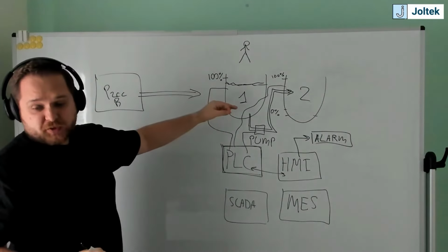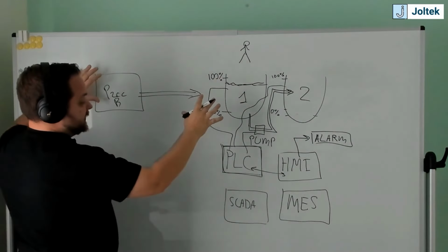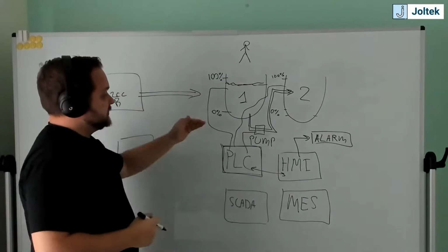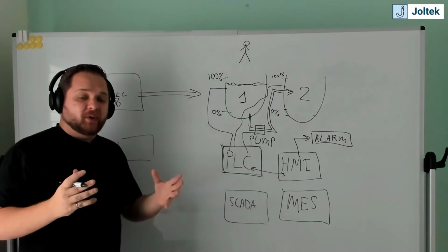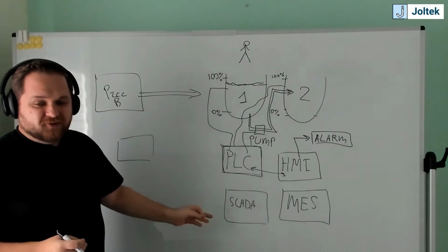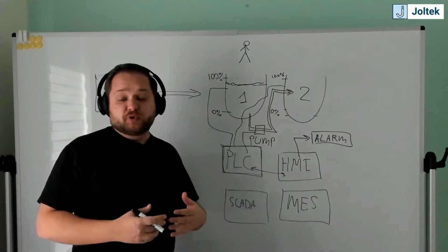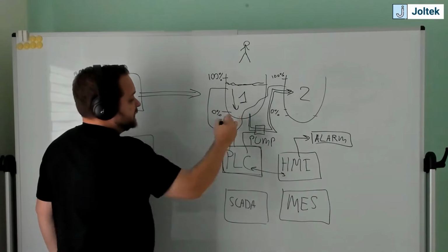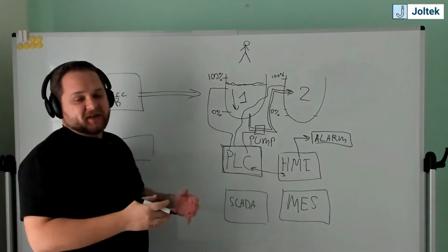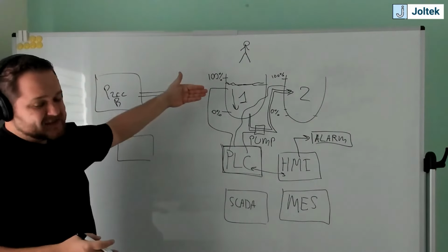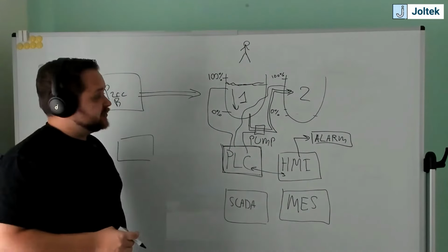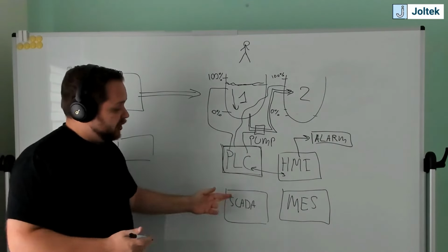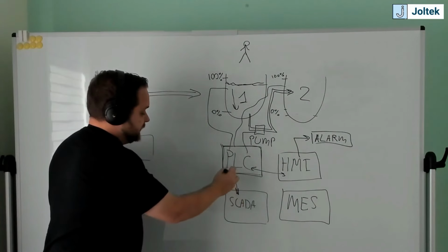that feeds into this first tank, then I need to look at a couple of different areas, how things are operating, so that I could tell the PLC from this process to start the batch once this operator empties out tank number 1. But anyways, the point is that at the SCADA layer, you can have a time delay between the response, because here when I start emptying this tank, I now know that I can, within, let's say, 10 minutes, start putting in the next batch into that first tank of this specific area. So there could be some delay as to how often the PLC will update the SCADA system.